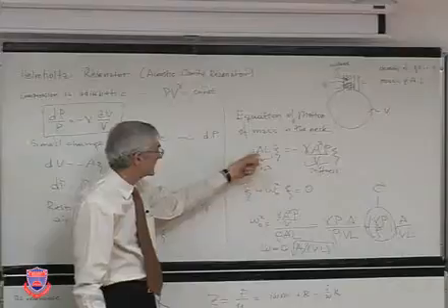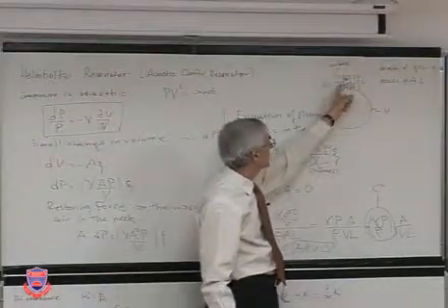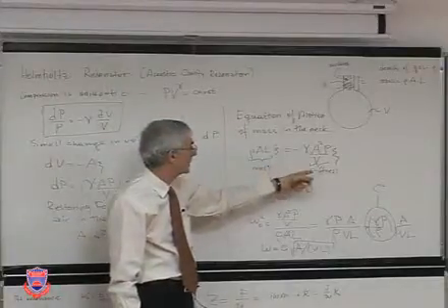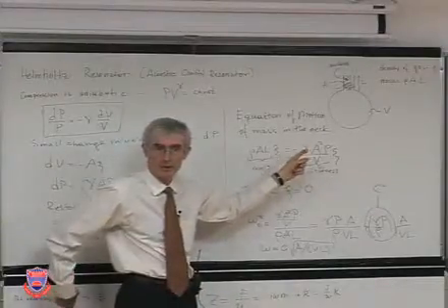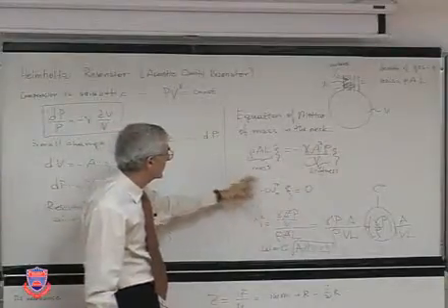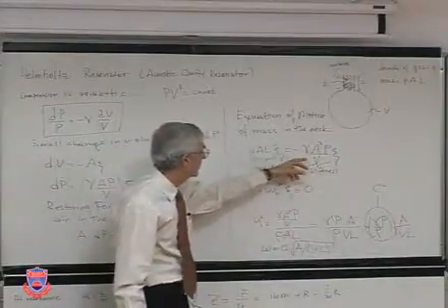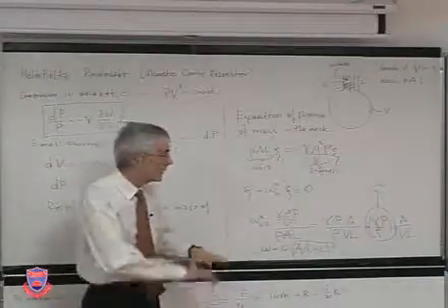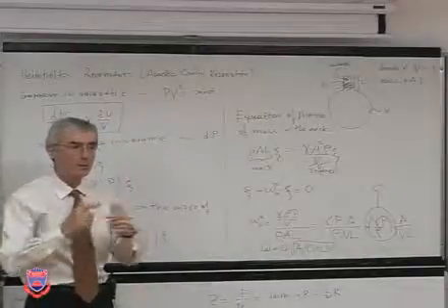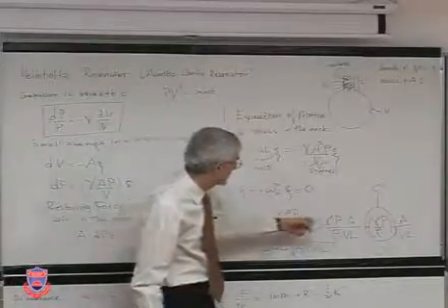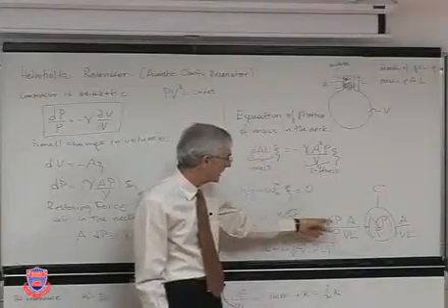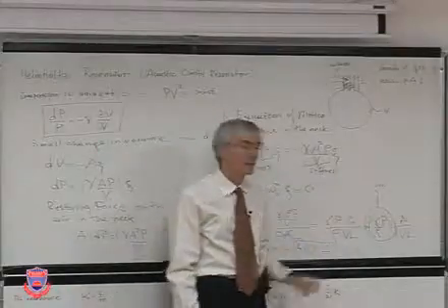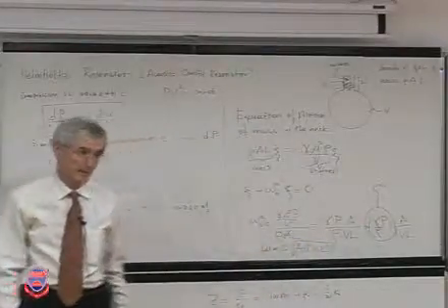Well, the mass itself is density times A times L, and its acceleration. And the restoring force we have already just found. Then what we do have is stiffness divided by the coefficients. When you divide them, it gives you the natural frequency of the system. But what is interesting here that you probably did not know before is that the ratio of the specific heats multiplied by pressure divided by density is equal to the square of the speed of sound.